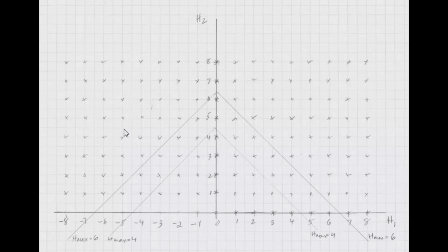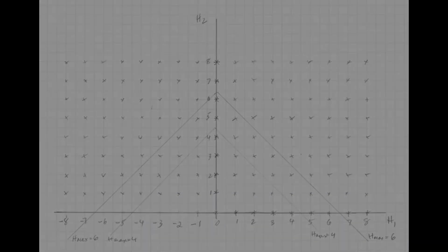You don't want to have, say, 4 and 5 gigahertz tones. If you have that situation, you can just offset the frequency of one of them to, I don't know, 4.7, something like that, and it'll work a lot better. And I'll say a little bit more about this when I show you some examples.